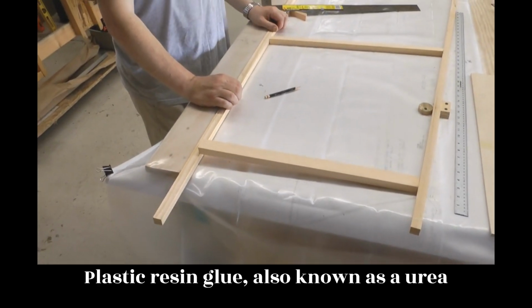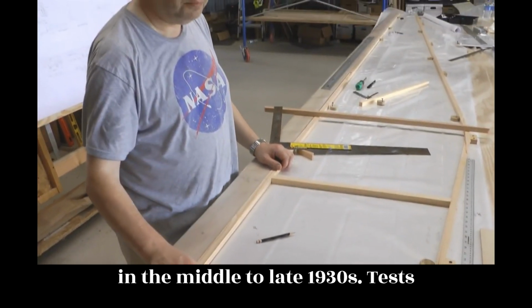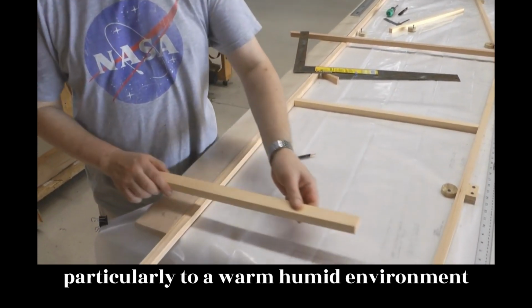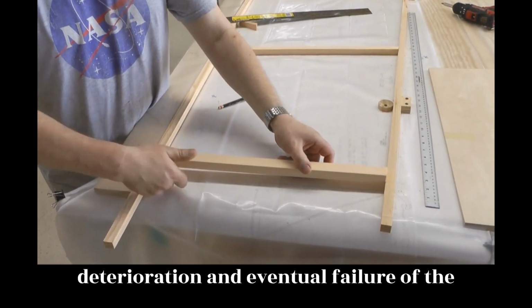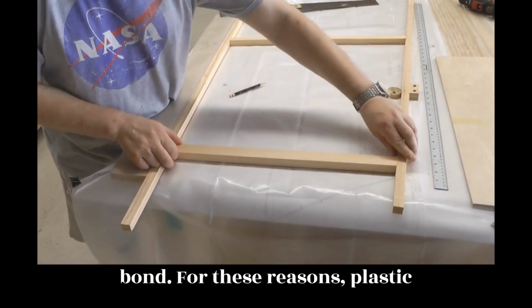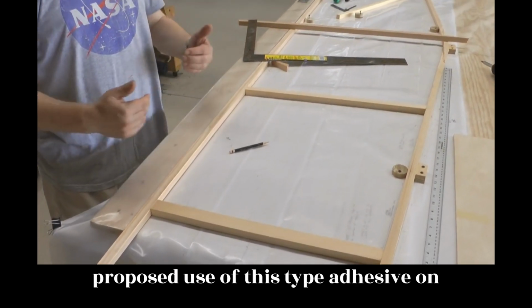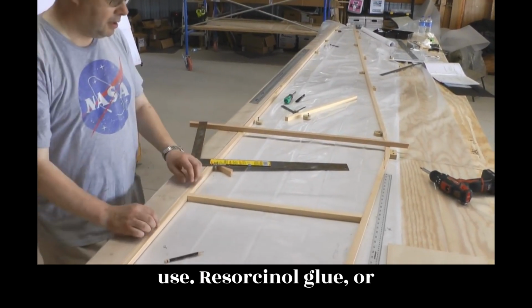Plastic resin glue, also known as a urea formaldehyde adhesive, came on the market in the middle to late 1930s. Tests and practical applications have shown that exposure to moist conditions, and particularly to a warm humid environment, under swell-shrink stress, leads to deterioration and eventual failure of the bond. For these reasons, plastic resin glue should be considered obsolete for all aircraft repairs. Discuss any proposed use of this type of adhesive on aircraft with FAA engineering prior to use.